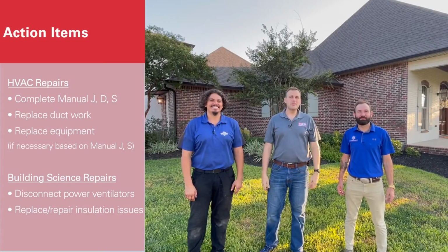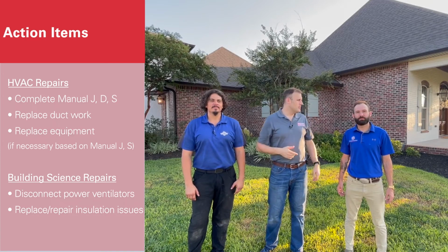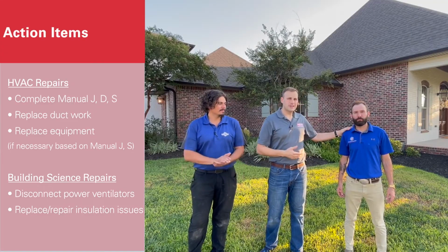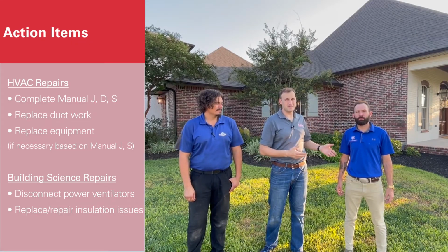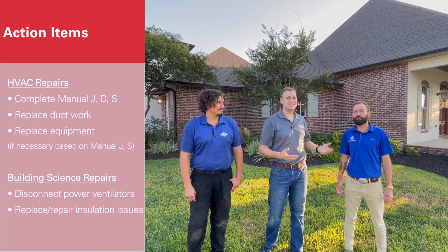Okay, so that's the home assessment on the house behind us. We hope we gave you some insight from the HVAC perspective, which we had Cody do a total duct leakage test, and then he did a true flow test, identifying that we have some major ductwork issues that we need to tend to, and the proper solution would probably be just replace the ductwork based on a good design.